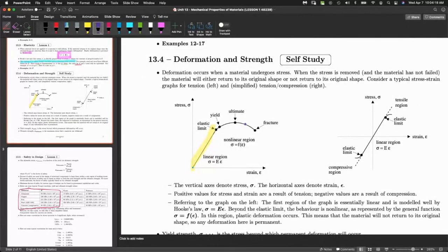But if you take an elastic band, and I know many of you have tried this, I want you to imagine pulling on an elastic, but if you do it slowly enough, do you know what happens to the elastic? Have you ever tried that? You might notice that it starts to change color. It maybe smells a little bit differently. It permanently is changed. And when you let go of it, it doesn't bounce back anymore. So that's what's called plastic deformation, meaning that you've permanently deformed the material.